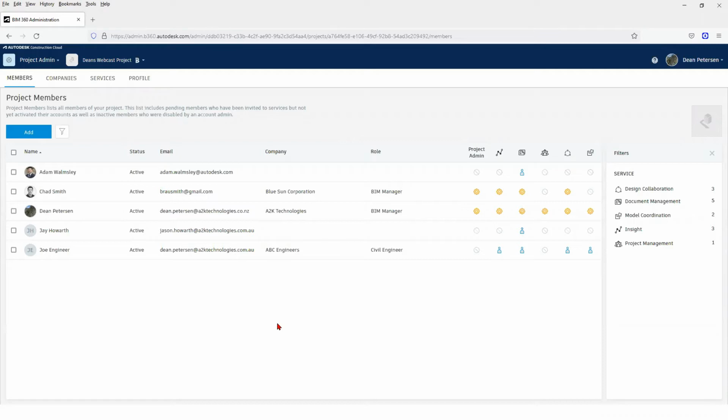So you can actually, for each of these files that are in here, give it a 30-day public link. You do have to be careful with that because anybody with a link would be able to see it, I think. But it is possible if you want to, if somebody doesn't have a license and you want them to be able to see a particular, or get access to a particular file, you can turn that on and do that, but it's off by default.